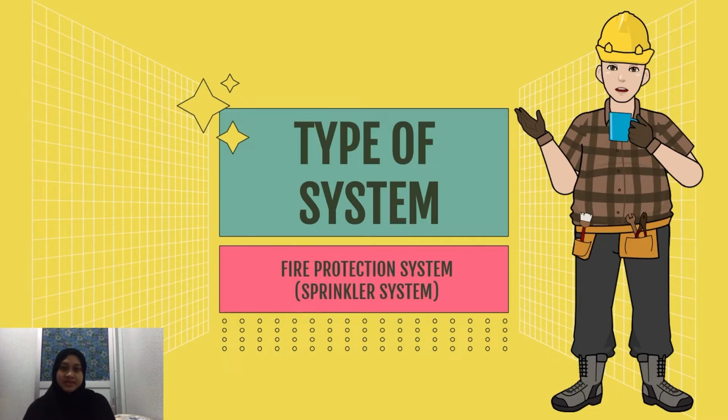2. Dry pipe system. Used in unheated or unoccupied buildings in conditions where pipes may freeze and burst. 3. Deluge system, commonly used in areas where rapid fire damage is a major concern, and opens a water release valve, and the nozzle is always open in this system. 4. Pre-action system, a combination of wet and dry pipe systems. The water in the pipes is not stored until a fire is detected, at which point it is released to the sprinkler.